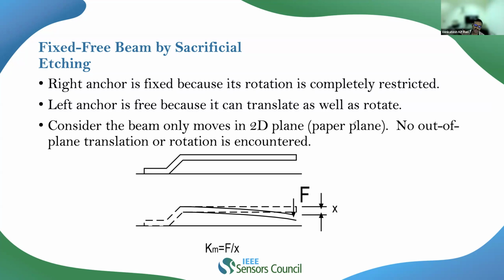Now, if you are realizing by surface micro machining, then one can get the bottom electrode below this. On the other hand, with your process, note that you are not going to get any bottom electrode. I'll explain that whenever you go forward for your fabrication session.